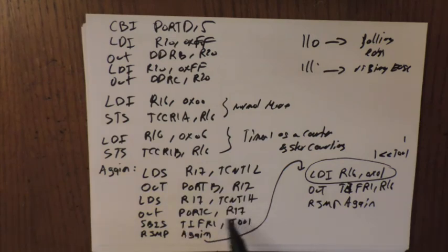Once I reach 65535 and 65536, this will overflow. I need to reset it before starting again. So you notice here I keep on doing it unless TOV1 is 1. Once it's 1, I reset the flag and continue doing the same thing again. This finalizes our lecture for timer 1.